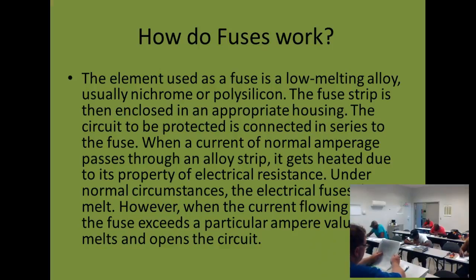An infinite resistance reading indicates an open or blown fuse. Now, this looks like a test question. A resistance reading of anything above 0.1 ohms indicates a burned fuse that should be replaced. Yeah, maybe it's not blown all the way. They're saying it's bad.